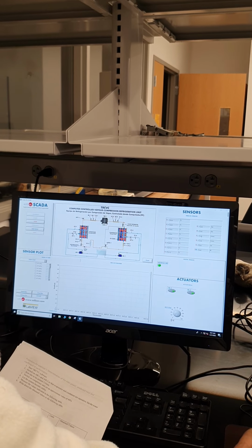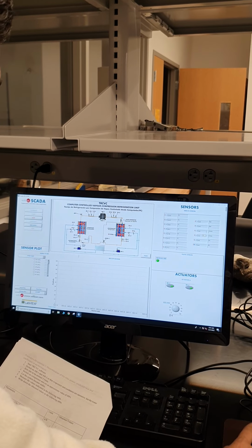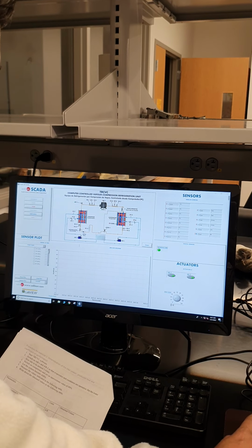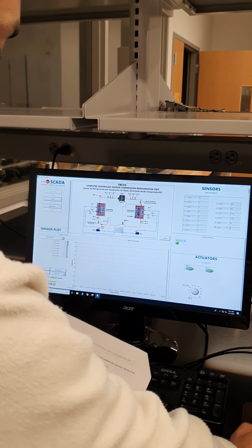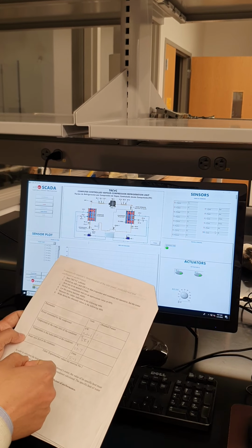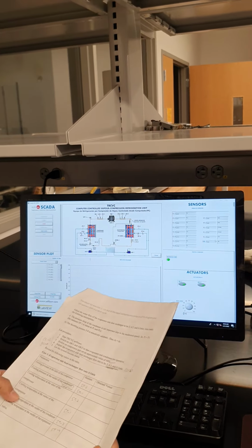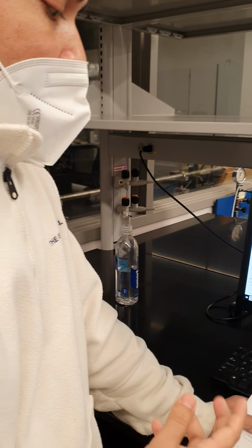First you need to set a flow rate of 5 liters per minute in the condenser side, and 5 liters per minute in the evaporator side. When you find the value on the screen, you need to record it in your experiment table. After that, we will carry out 3 cases of our experiment.